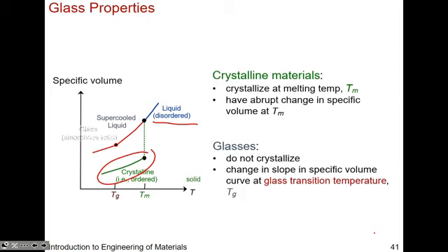Because they don't crystallize, we don't expect them to go to some close packed structure. What really happens is it undergoes this period between the melting point, TM, and the glass transition temperature. That's a new term. So it goes through what's called a supercooled liquid. You're just cooling it down, and it's in this area that's just called supercooled liquid. It's still sort of liquidy, viscous, and then it goes through a temperature that's called the glass transition temperature, and the temperature drops.